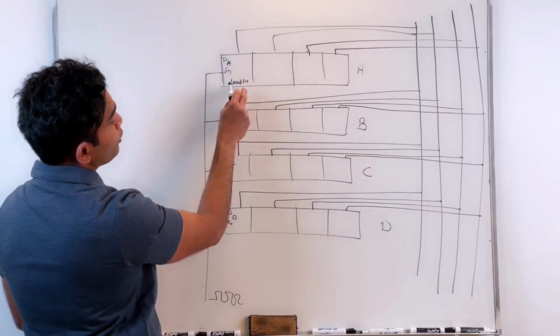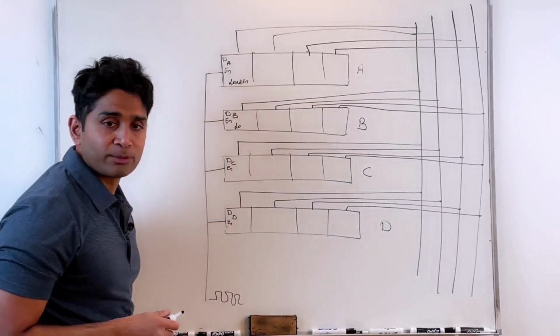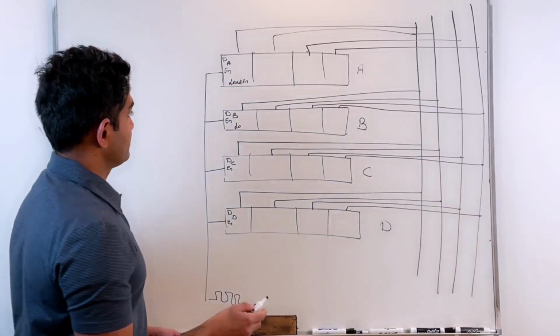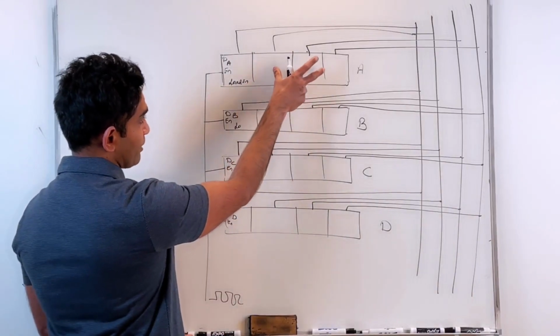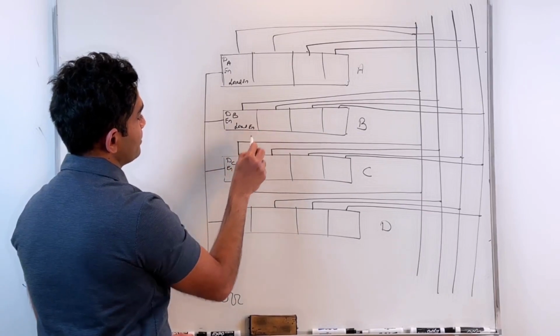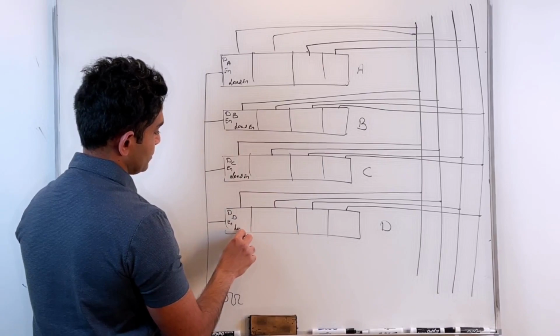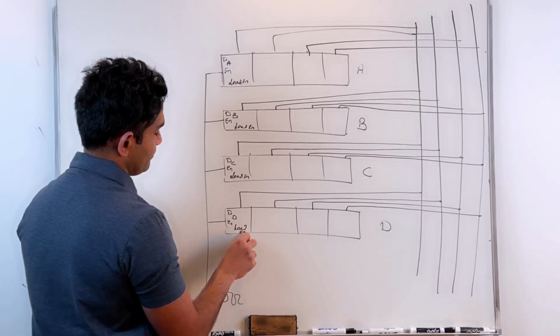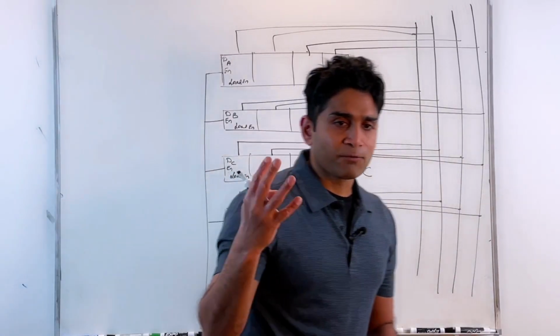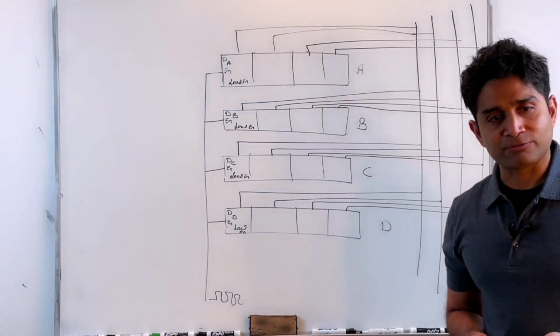Although I'm showing it as 1, you can imagine that each of these has similar load enable inputs. All of them are connected together for one particular register. Load enable input. Okay, so I have 4 registers, and I want to come up with unique addresses for each register.